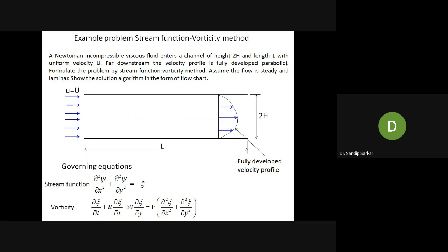Basically, this is a standard example of a convection diffusion equation, where we have a temporal term, basically the time dependent term. This one is a convection term, basically the movement of any property. Here the property is your vorticity, moved by the fluid due to the fluid motion. Fluid motion along the u and v directions, that is along the x and y directions, causes movement of the property zeta along the particular direction. So the movement of this property by the combined consequences of velocities is called the motion of this particular property. That's why it is called convection. Similarly,